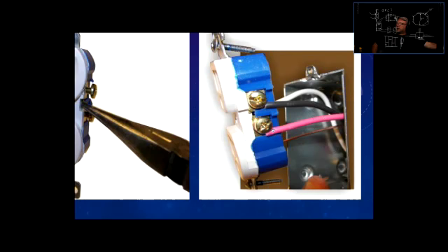So here's the jacket. It is pinched by the screw terminal, so most of the connection is being made with the insulation, and some connection will be made with the bare copper wire. What is going to happen then, there's a chance of not a very tight connection being made. Yes, too short inside as well. When that happens, this is the weakest point in this case, things might heat up a little bit to the point that you can actually start a fire, right? Or arcing, yes. All right, there we go.